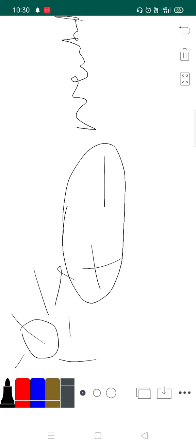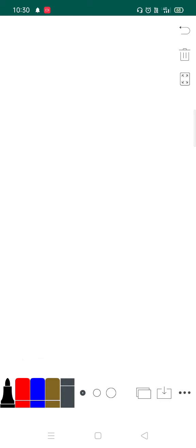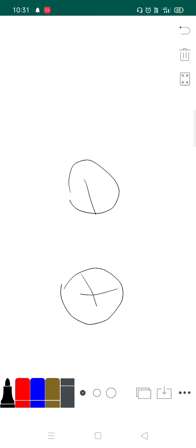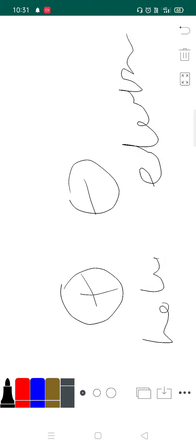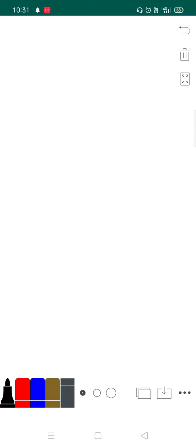Okay, so when sunlight falls on the neutral atom, this neutral atom will be broken up. This is the hole, this is the electron. This knocks the electron from the neutral atom, leaving behind the hole and producing the free charge carriers. Then these free charge carriers, like electrons, move towards the n-type layer.